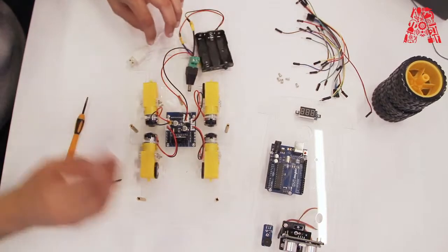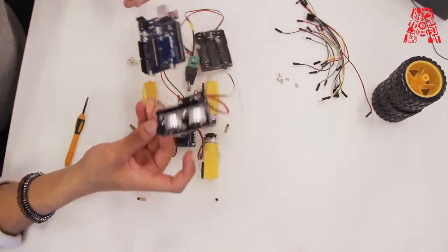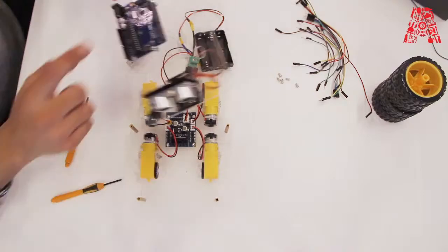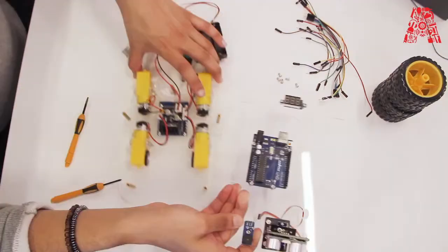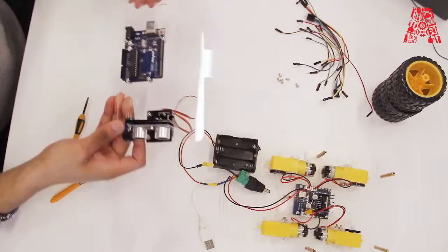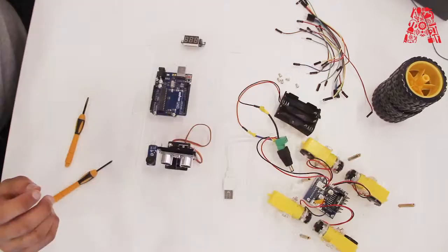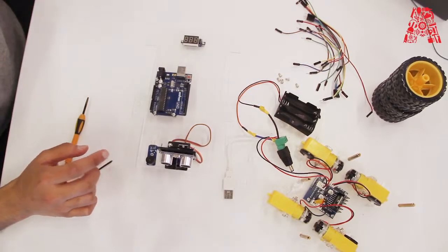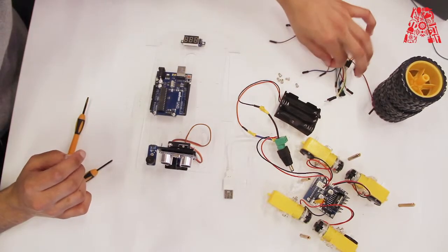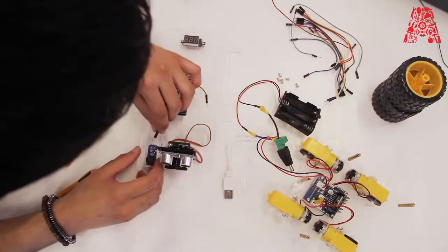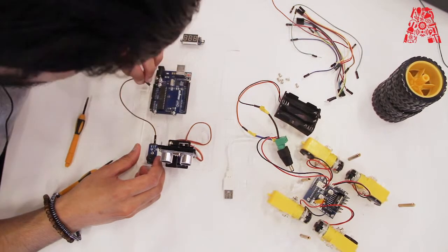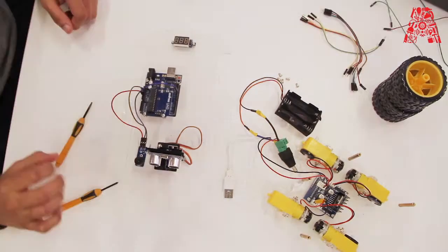Let's move on with the connections with the ultrasonic sensor, the buzzer, and the voltage meter with the motor driver and Arduino. Alright, so let's make the connections with the Arduino first, then we will make the connections with the motor driver. First, we will make the connections for the buzzer. And we're going to be using these jumper cables. So the VCC for the buzzer will go into 3.3 volts of the Arduino board. Now the connection for the buzzer has been done.